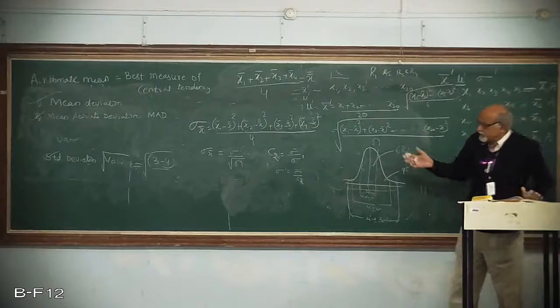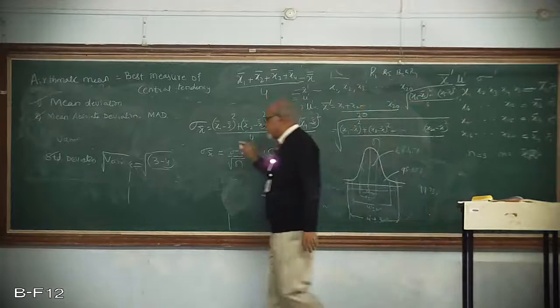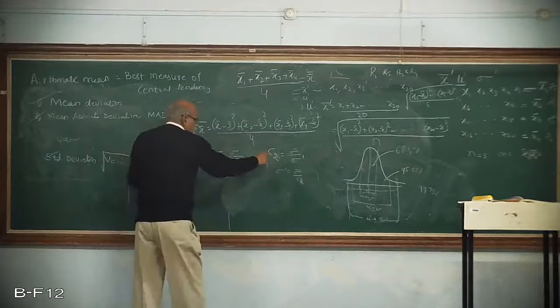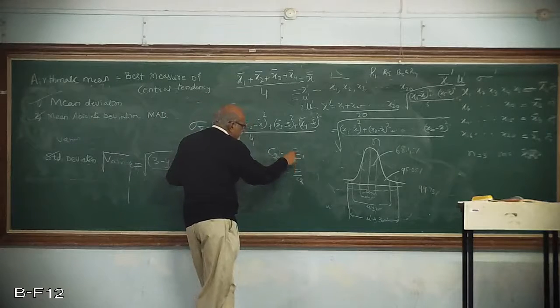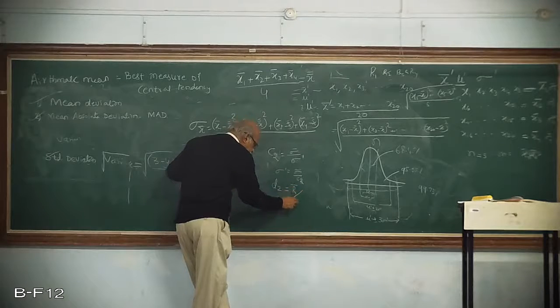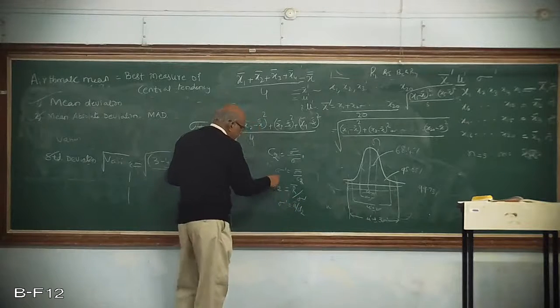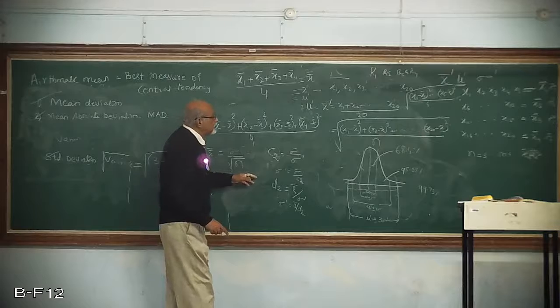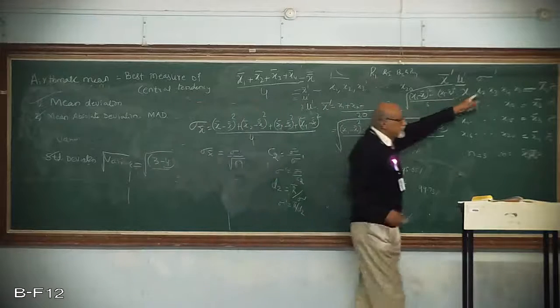Now, he has also established how this is connected. Like sigma bar is connected to the universal standard deviation, similarly he defined a factor for sigma. Again, D2 is the factor which will depend only on the subgroup size, that means how many samples I have taken to make one group.